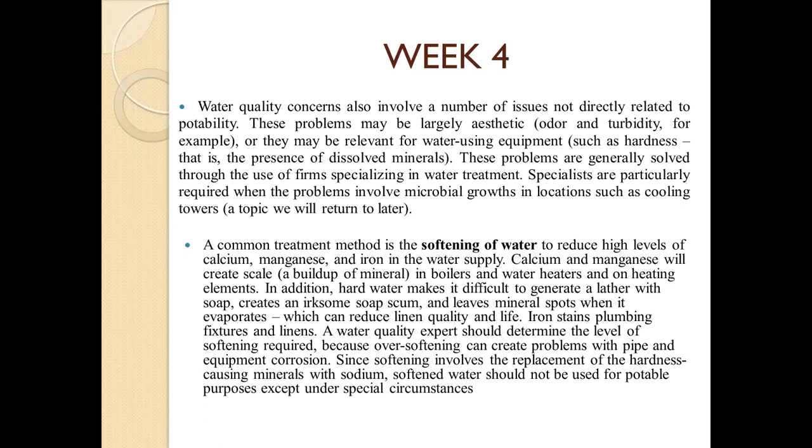Okay, water quality concerns also involve a number of issues that are not directly related to potability. These problems may be largely aesthetic, odor and turbidity, for example, or they may be relevant for water using equipment such as hardness that is present or dissolved minerals. These problems are generally solved through the use of firms specializing in water treatment. Okay, a common treatment method is the softening of water to reduce high levels of calcium, manganese, and iron in water supply. Calcium and manganese will create scale, a buildup of mineral in boilers and water heaters and on heating elements.